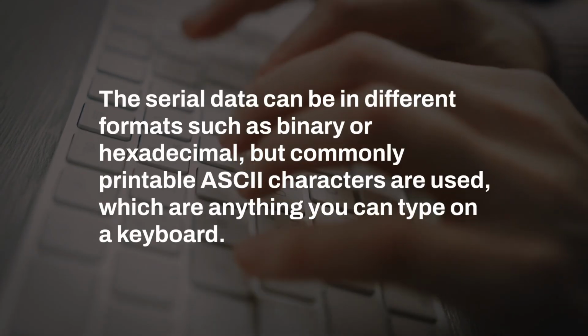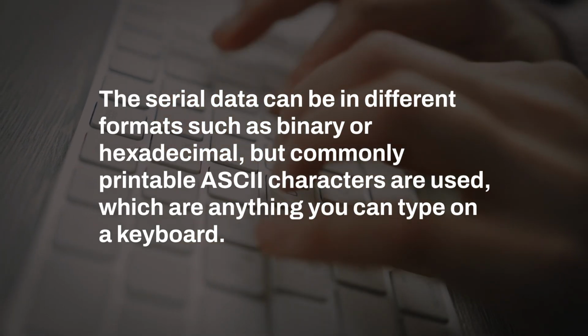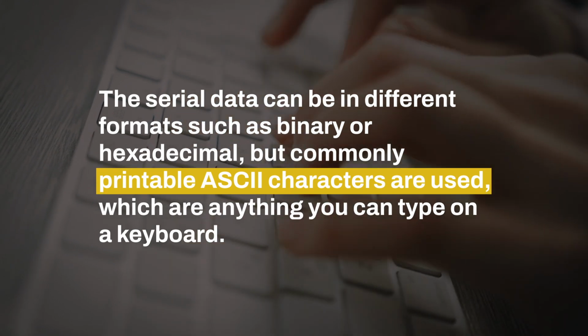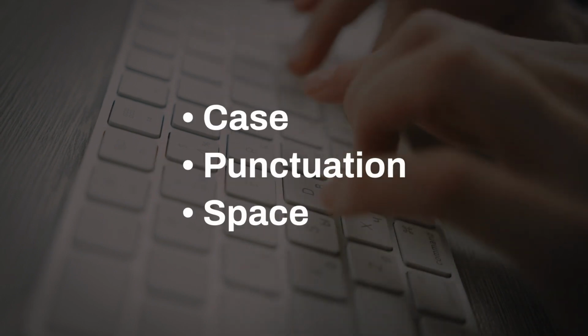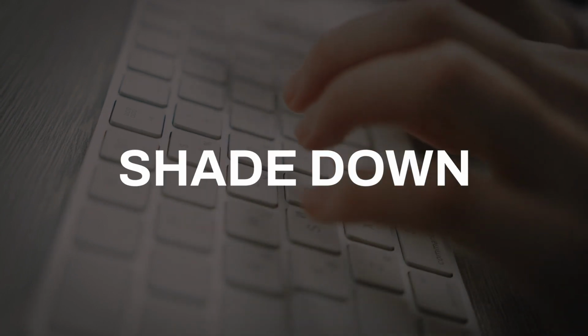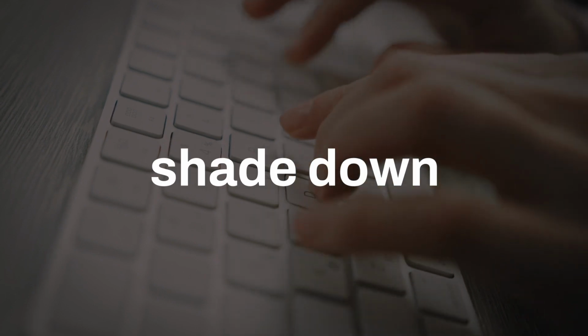The serial data can be in different formats such as binary or hexadecimal, but commonly printable ASCII characters are used, which are anything you can type on a keyboard. The ASCII characters are combined together in a string format. An example of an ASCII string would be the words "shade down." The strings are case, punctuation, and space sensitive. This means that the word "SHADE DOWN" in all caps is not the same as "shade down" in all lowercase.